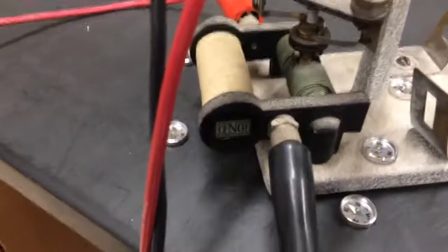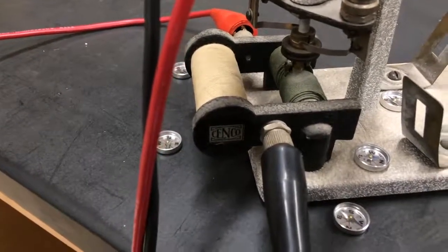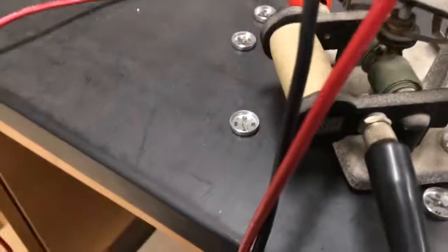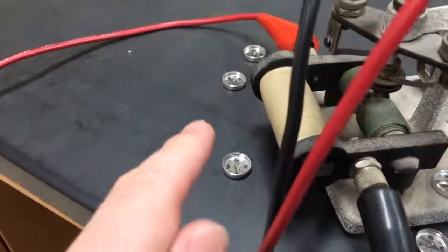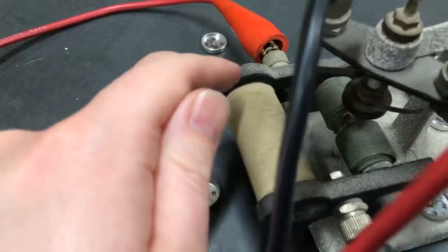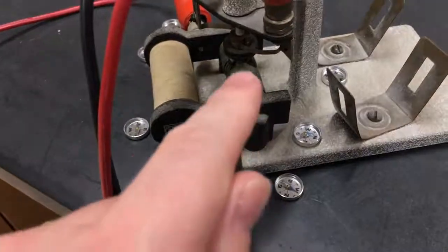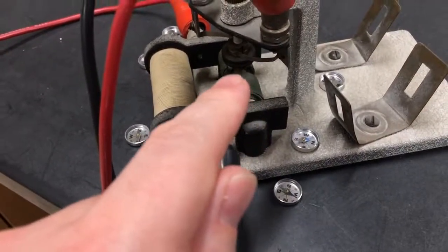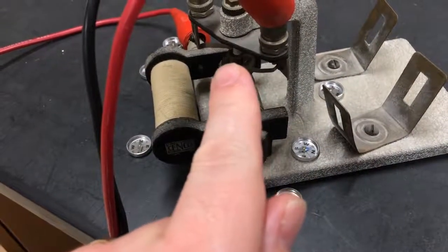So first of all, there's this tan coil of wire, and that's an electromagnet, and these compasses tell us about the direction of the magnetic field. It's apparently coming out of this end, looping around, and then pointing back in here. So by symmetry arguments, we can assume it's doing the same through the spinning part of the motor, and the magnetic field is pointing in the direction I'm pointing away from the camera.